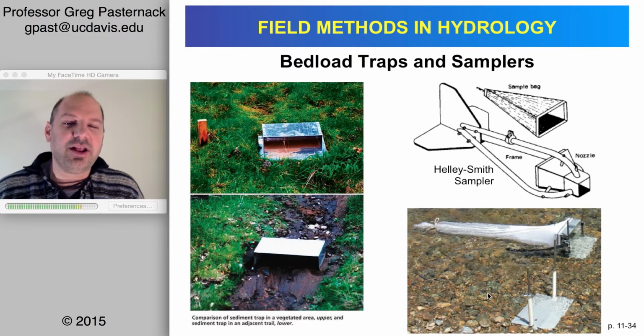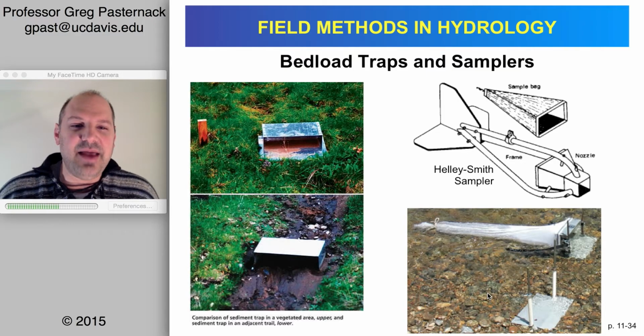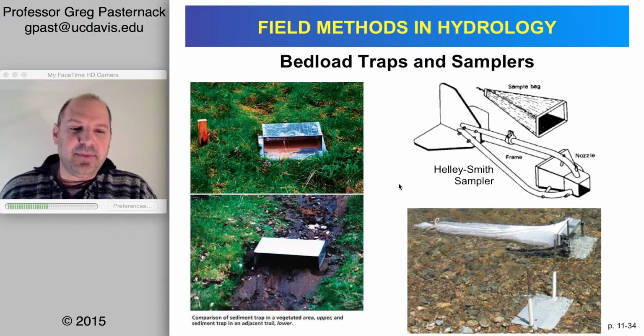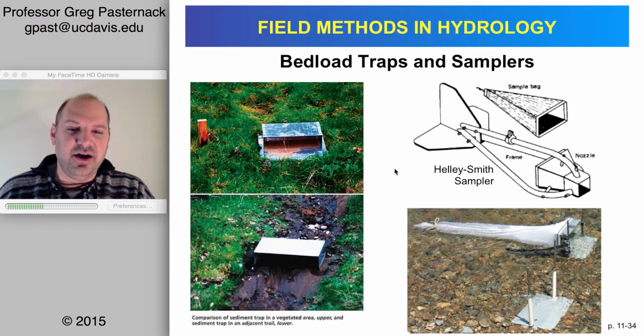Oh yeah, there are dedicated suspended sediment samplers. I'm not covering that right now, but I did want to mention bedload in particular because it's a little bit more tricky to do, and we're talking about what's going on at the surface more than the flux in the water column. We'll get to that when we talk about water quality and turbidity. But bedload usually is not part of water quality, which is why I'm covering it here.